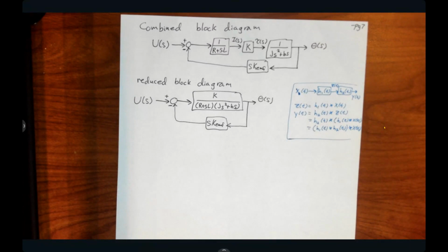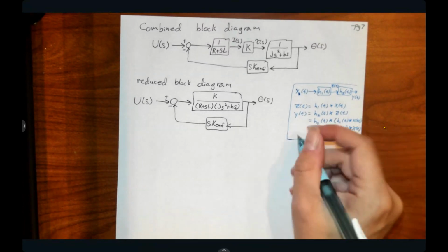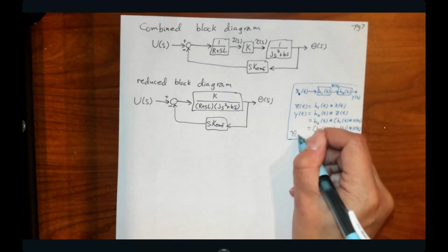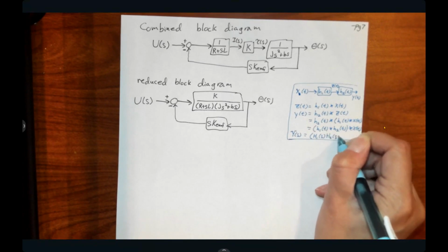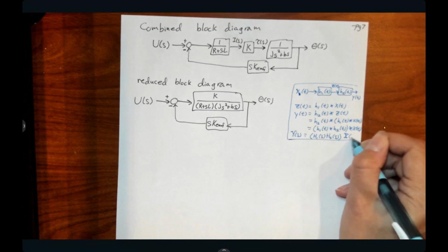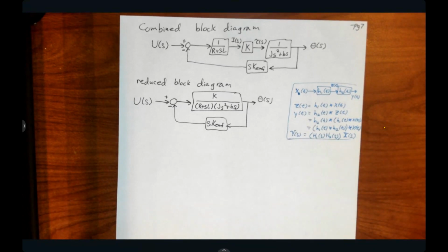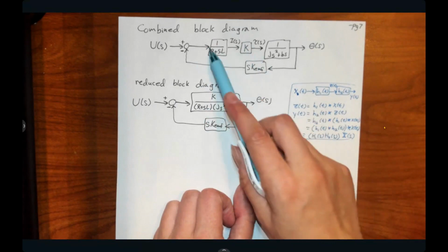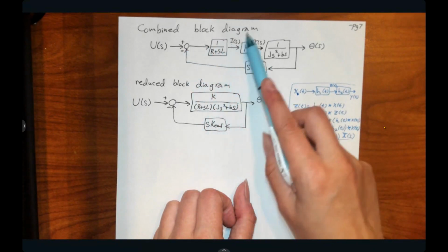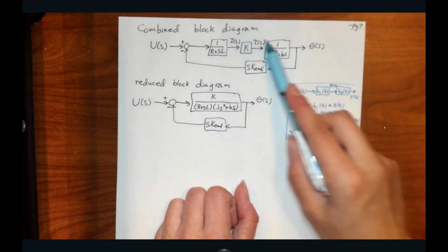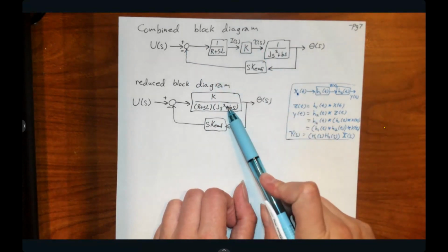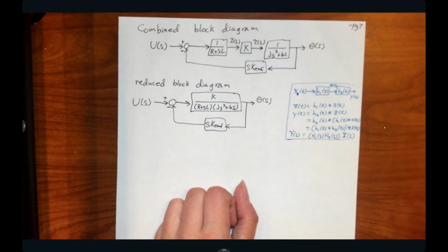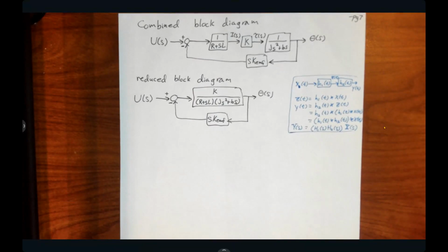We have this convolution. So in the frequency domain, you could express this as h1 times h2, because convolution in time becomes multiplication in frequency. And so that's what I'm doing here. We can see that this input feeds into one, feeds into the next, into the next. So I can reduce this down. Instead of having three separate transfer functions, I can combine them together into one single transfer function. And it turns out that I can actually reduce this a little bit further.